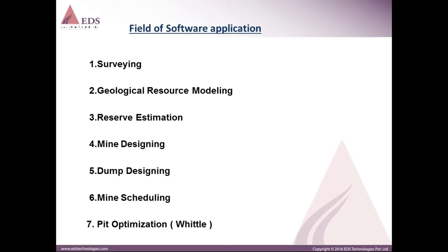So you have to dump it in your mining lease area only. For that, you have to design your dump area, and see whether the waste material will be accommodated in it or not. And then coming to mine scheduling, you have to schedule your mines before going for day-to-day planning or weekly planning. For that, mine scheduling will be required,